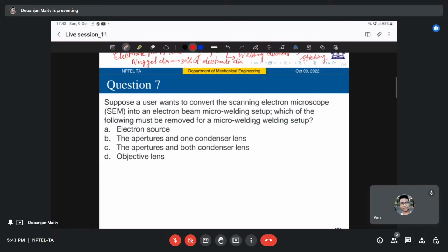In conventional laser welding, a gap between the parts is a common research gap. It cannot fill the gap between the parts, and it worsens the quality of the laser welded joint substantially. But contrarily, a droplet offers sufficient material to bridge those gaps. Even different gap sizes can be bridged by a suitable selection of the droplet size.